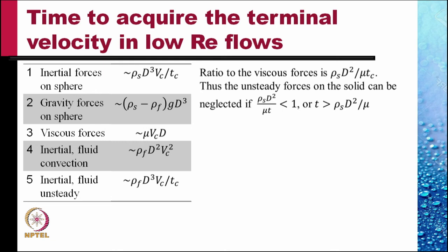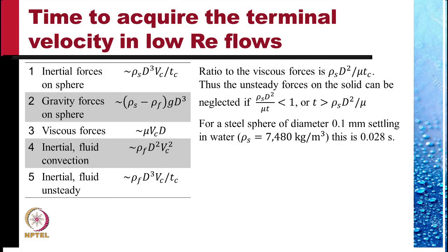We can neglect it if t is greater than this. So, for time less than this, we need to consider the unsteady forces. For a steel sphere of diameter 0.1 millimeter settling in water, this is 0.028 seconds, a very small time.